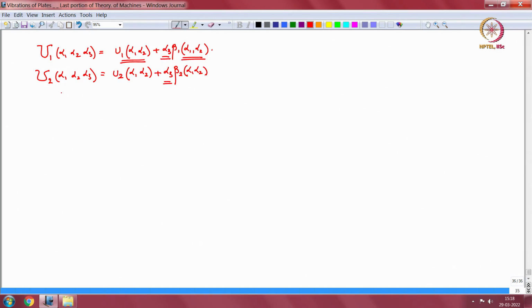Then because it is thin, u3 in the alpha 3 direction is uniform across the thickness, so it will be given by u3 of alpha 1, alpha 2. So there is no change. In the thickness direction, this whole thing moves in unison. There is no change in the thickness. As a result, immediately epsilon 33 is 0. Epsilon 33 is 0.